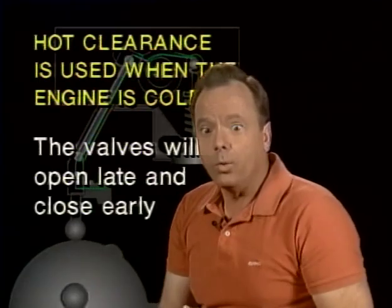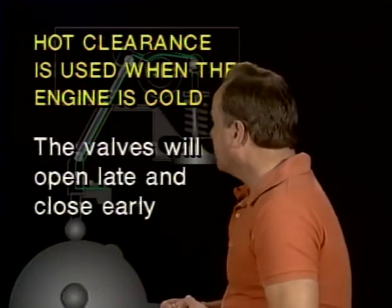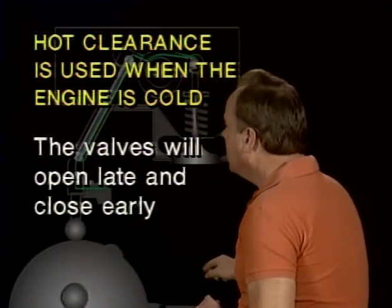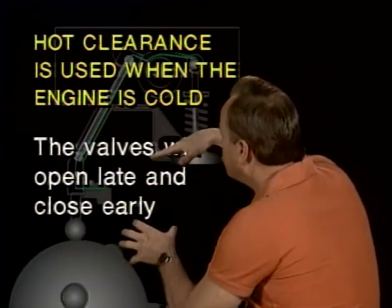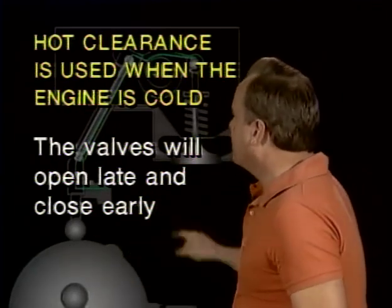So if you use the hot clearance to set the valves, but the engine is cold, what's going to happen? The answer is the valves will be misadjusted. They will open late and close early because you've got too much valve clearance. So when the engine is cold, you cannot use the hot clearance to set the valves.